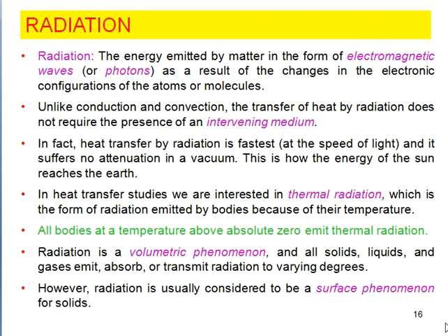Then radiation. Radiation is a mode of heat transfer in which heat transfer takes place by electromagnetic waves, which we can also call photons. It occurs as a result of changes in the electronic configuration of the atoms or molecules. Here radiation does not require any intervening medium. For conduction, a solid medium is required. For convection, a fluid medium is required, either liquid or gas. But here no medium is required; radiation heat transfer takes place even through vacuum.